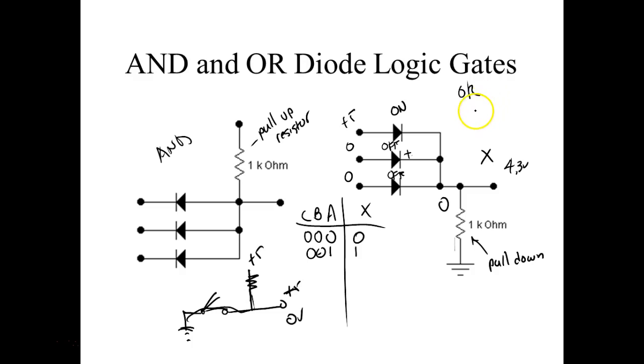Now listen over here, what I'm trying to do is come over here and hook this up to plus 5 volts. And over here, if I didn't have that resistor there, that right there would be hooked to common, right? You understand? I close that switch, I have a short circuit. If I put a resistor right there, if I close that switch, I get plus 5 volts. If I open that switch, there's no current flow through that resistor. The resistor's not going to drop any volts, and it would give me 0 volts out.